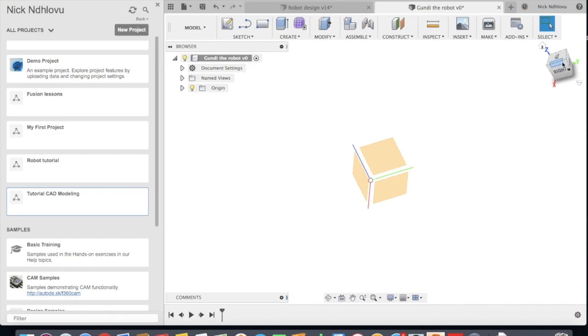All right. So I'm going to go ahead and view it normal to this view. So I'm going to click here. Then I'm going to view it normal to that. Then here you'll see another icon of a hand. And if you click on that, you will be able to pan around. So you'll be able to drag your model around the screen or around the canvas. And if you let go, you can exit that.